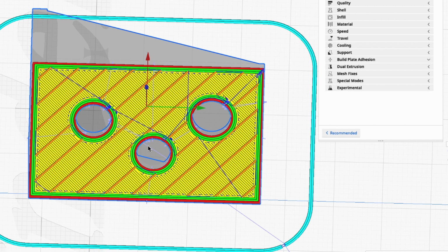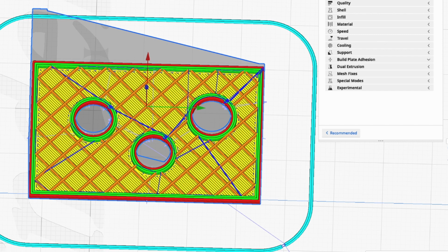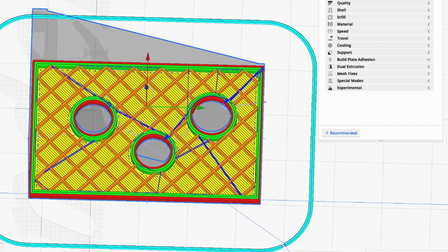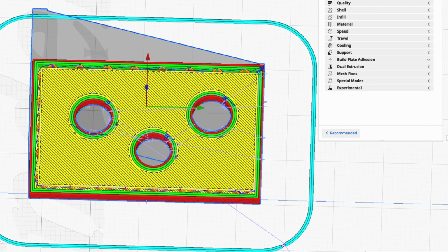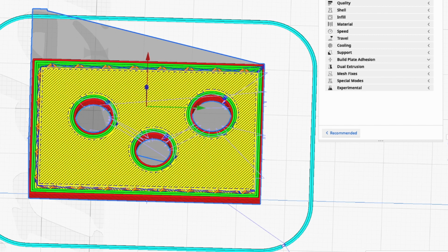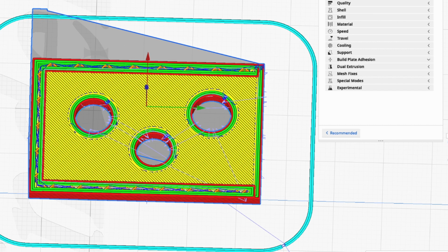And then those orange lines are infill. That's what they call infill. So think of it kind of like internal supports. And that's actually probably a lot of infill. And then it's going to do another top layer. So the infill is so that it's not a solid object, because if it was solid, it would take even more plastic and weigh more, and you don't always need it to be solid.